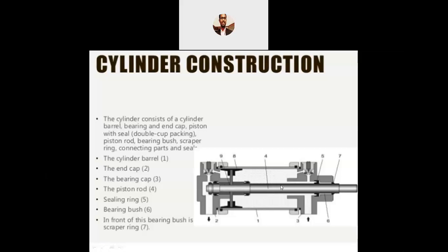Meanwhile, in order to check the leakages which are possible in these pneumatic systems, proper seals and bushes are used. The bushes will perform functions. One is that it prevents the leakages, and the second is that it will absorb the shocks. The third is that it will also facilitate a proper lubrication effect for the